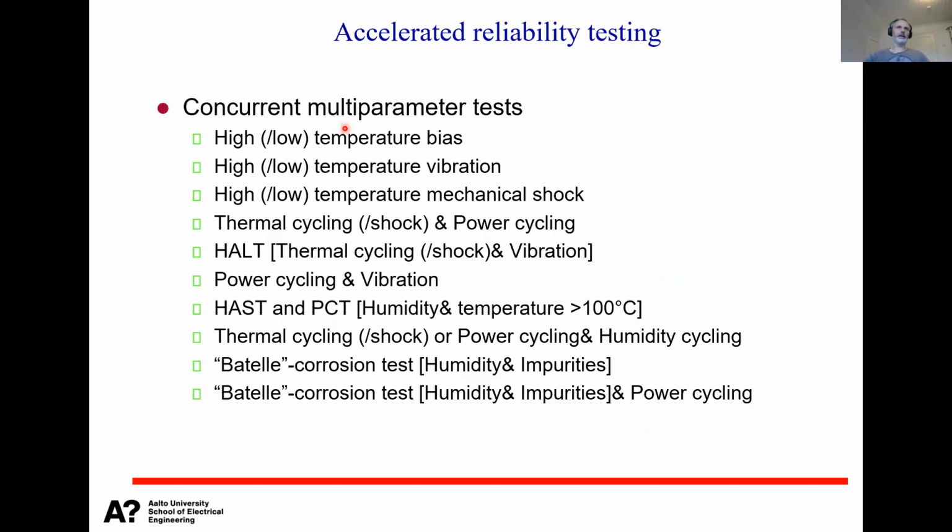So it could be that you have either high or low temperature, and then you have some electrical stress or some mechanical stress. For example, you are doing your vibration testing at different temperatures, or you are doing your mechanical shock loading, drop testing, whatever, at different temperatures. Or you have your electrical biasing at different temperatures, or your electrical biasing under hot and humid conditions.